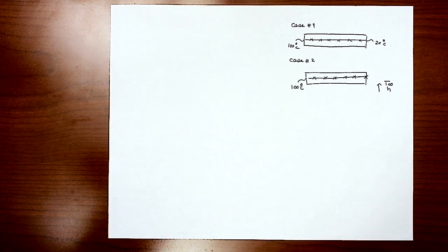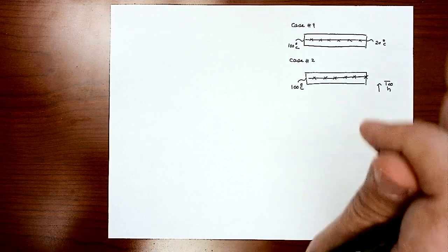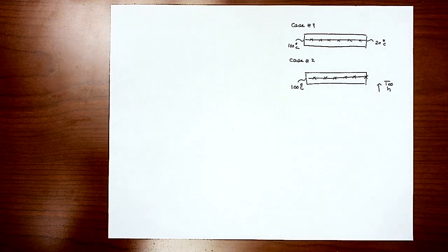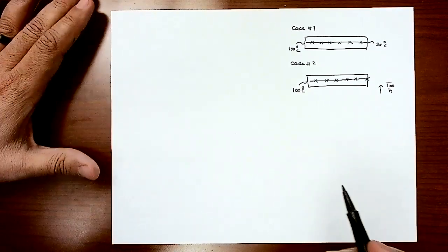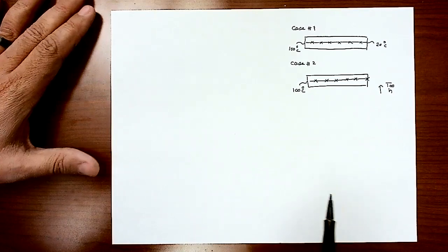And these are the very common cases that we're gonna apply solutions for when we deal with the finite volume method. So I'm just going through this example here using the finite difference method, but we will repeat the same conditions, going into two-dimension problems, using the finite volume method. So it's good practice to do that with these simple examples here.